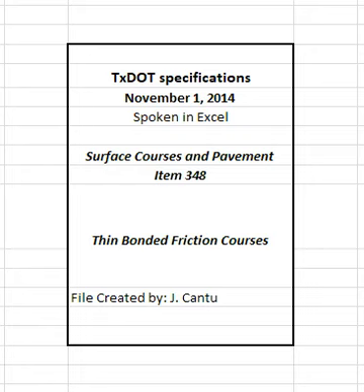4.4.2.1.3 Hamburg and Overlay Testing. Use an approved laboratory from the department's MPL to perform the Hamburg wheel test, and provide results with the mixture design, or provide 10,000 g of the laboratory mixture and request that the department perform the Hamburg wheel test. Provide 25,000 g of the laboratory mixture and request that the department perform the overlay test. The engineer will be allowed 10 working days to provide the contractor with Hamburg wheel and overlay test results on the laboratory mixture design.